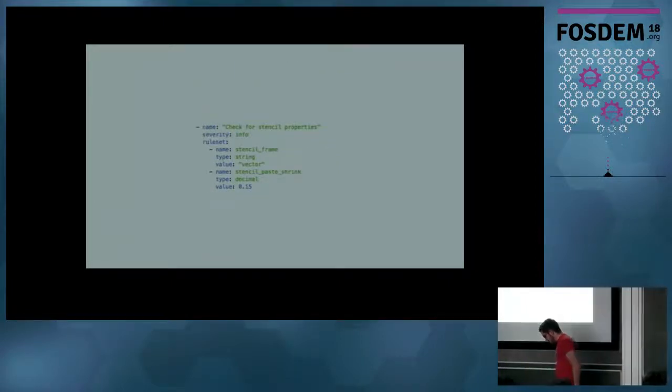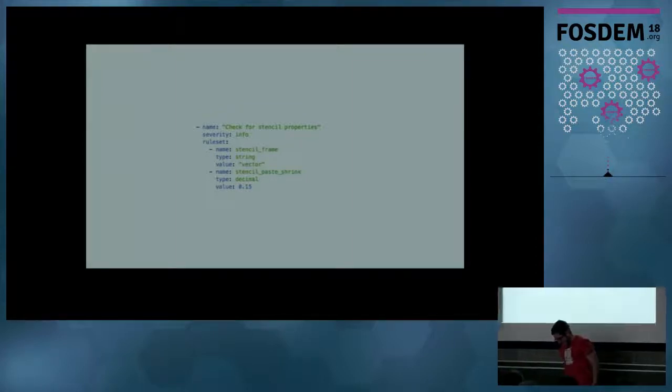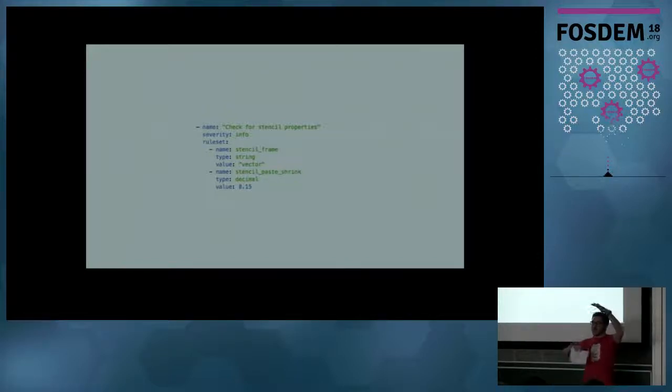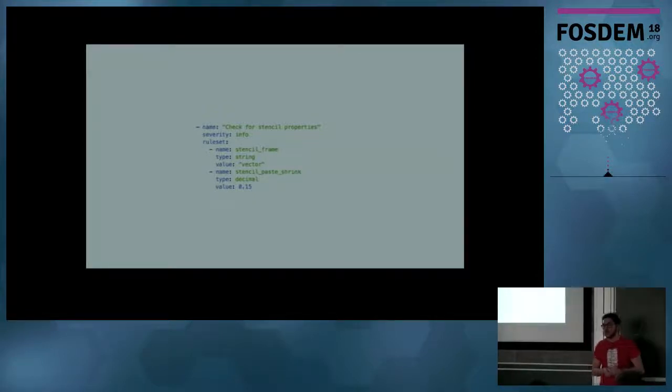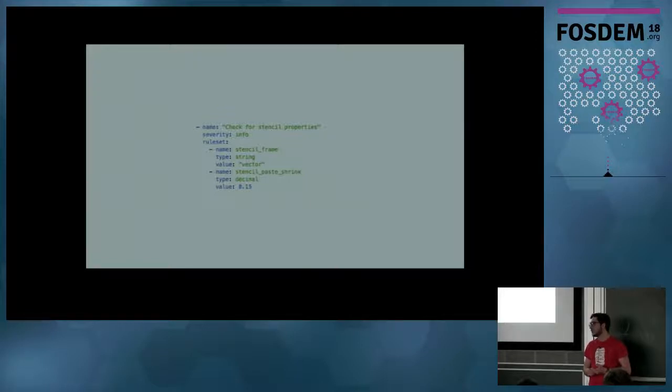Stencils are something really important, which a lot of people don't keep in mind. When you start producing a stencil for manufacturing, you don't have a stencil of this size, you have something which is much larger with a frame around it. And this frame is specified by the system they use for mounting the stencil. Please ask the manufacturer, which kind of mounting system do you use for your stencils? Type it in the design rule format, and then it checks every time, do you use this frame?